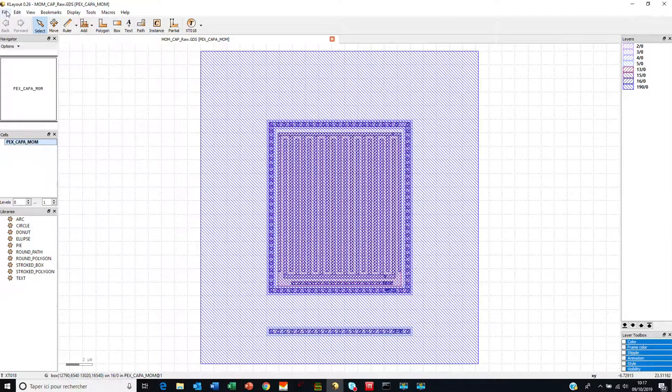The next step is to merge the data, since sometimes we have overlapping polygons and things like that. In order to simplify the database, it's a good practice to merge the layers. It is not the case here. The data are already correct. And finally, it can be a good practice also to snap the coordinates to a defined grid so as to minimize the size of the future meshed structure. A bunch of scripts can be supplied to make these operations easier.